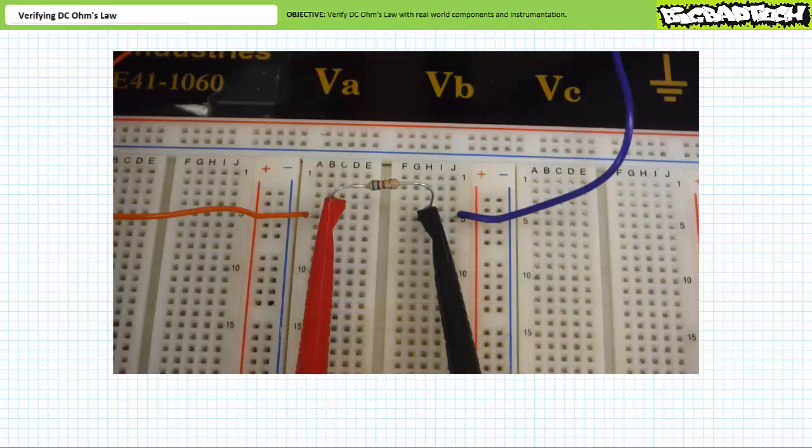This is not how you install an ammeter. You recall that ammeters must be placed in series or in line with elements of interest, such that all current passes through the ammeter. Placement of an ammeter in parallel with an element of interest can have disastrous consequences. Recall that ideal ammeters are modeled as 0 ohm resistances through which substantial current can flow.